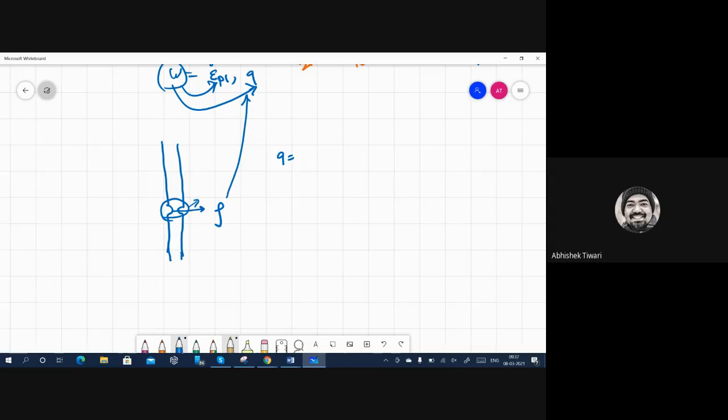So you can take a range of Q here, and that Q will be specific for the root radius which you have given in the simulation. Then you change the root radius of the notch and do the elastic simulation again and calculate different triaxiality values for different tensile specimens. And for all those, you have different stress strain diagrams.